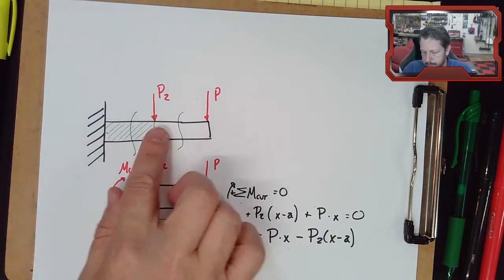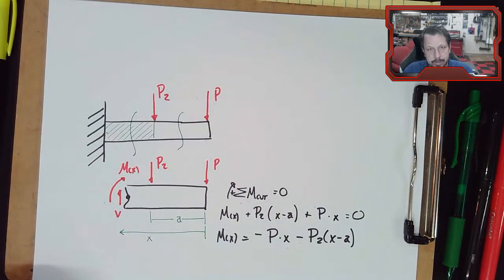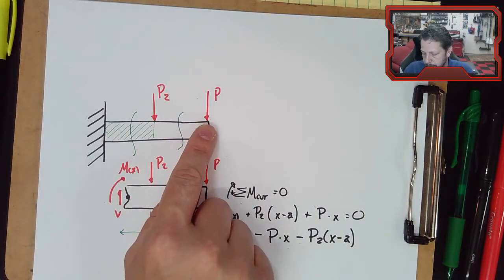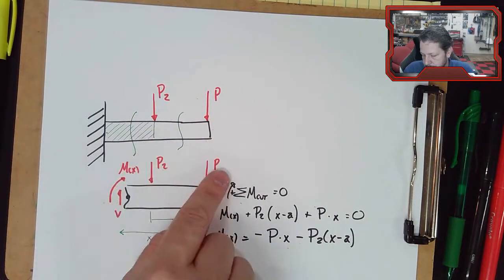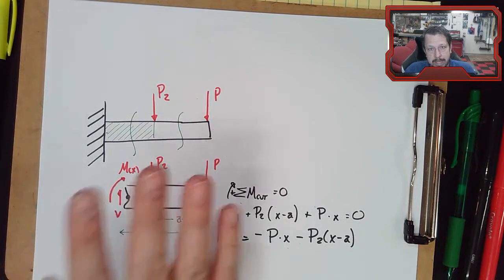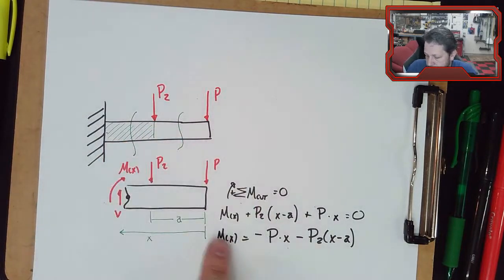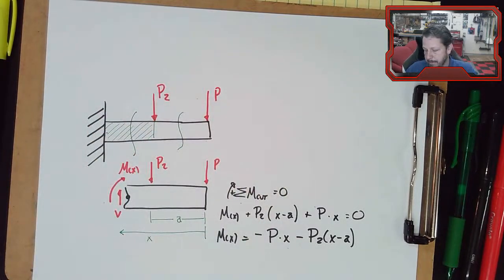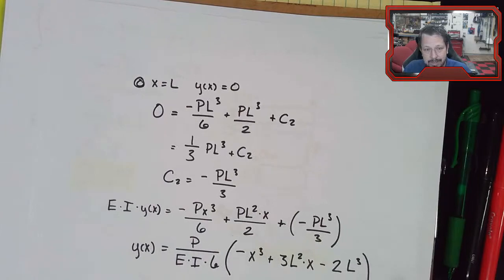to create a simple version of this. Like this would be really simple with superposition. It's 2 cantilever beams that you have to add together. One where the point load's at the very end, one where the point load's in the middle, and the rest of the beam just slopes downward. And you just add those together using superposition in case 1 in the charts that we looked at last time. So it's not that you have to develop the equation of the elastic curve to do every one of these beams. But it's useful to know, how is it coming? How do you get to this point? Where's it coming from? What are the assumptions that were made to get here?